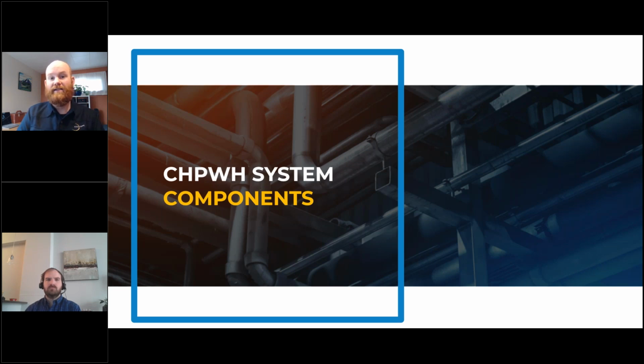Our mini split heat pumps, where we have one of those Mitsubishi, LG, Daikin heat pumps on the roof or in a garage, and a split system of ductless fan coil in the apartment space, is going to have about the same maintenance requirements as these heat pump water heating systems. Both are heat pumps extracting heat from the air, or in the space conditioning example, when we're cooling, we're trying to discharge heat to the air.